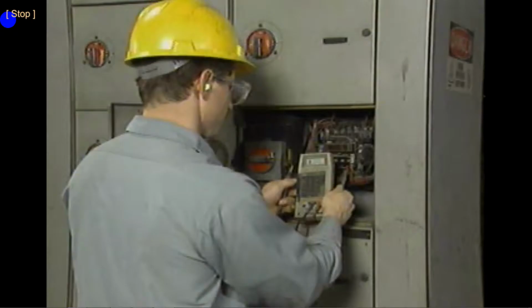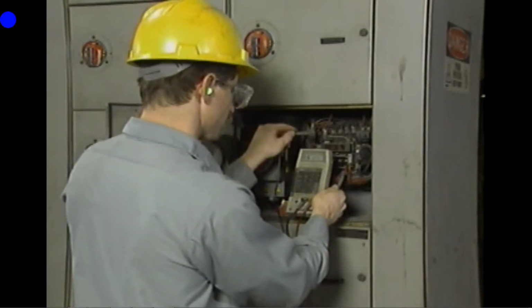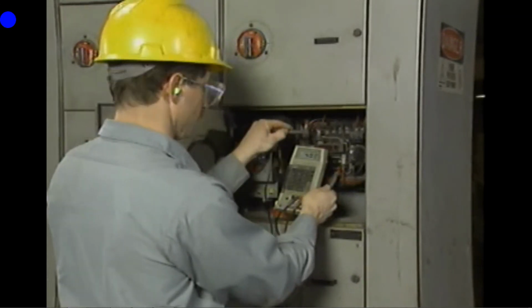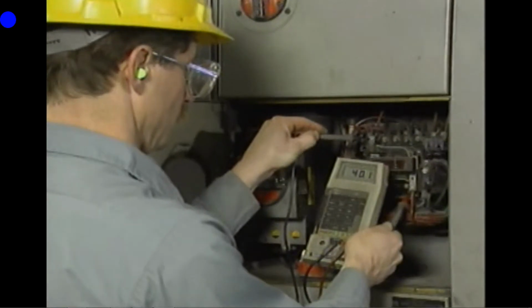So far, we've looked at how a de-energized controller can be tested for grounds and opens. The last type of test we'll look at is the test for shorts. Testing a de-energized controller for shorts is exactly the same as testing the controller for opens, except that the expected results are different. An open results in a higher than normal resistance reading, or infinity, while the reading for a short is lower than normal. To test for shorts, the electrician takes a resistance reading for each component under consideration.